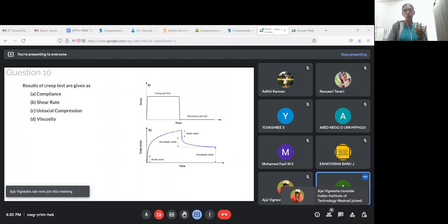So you will have a viscoelastic strain, that is your strain will slowly increase with stress. There is no sudden increase or no complete flowing. It will be somewhere in between the both, and you will have a strain that is slowly increasing with time throughout the creep period. And the moment you withdraw the stress, there will again be an elastic strain. That is, the moment you release the stress, the elastic part of the fluid will try to come back to its original position.